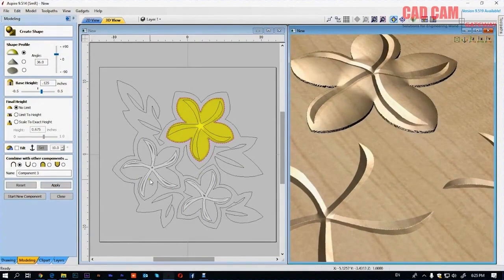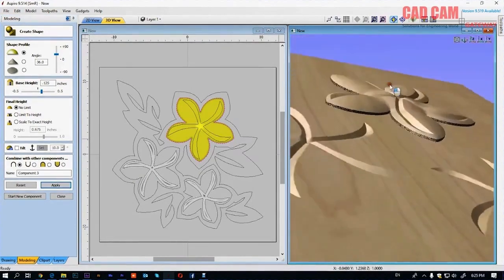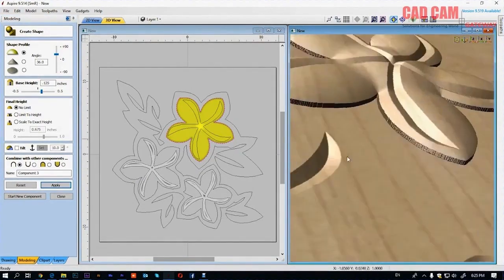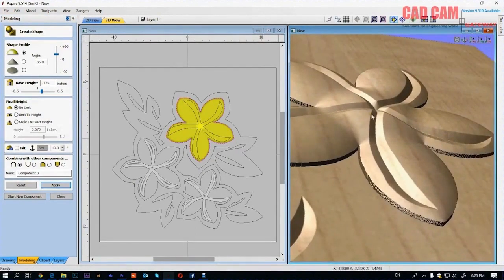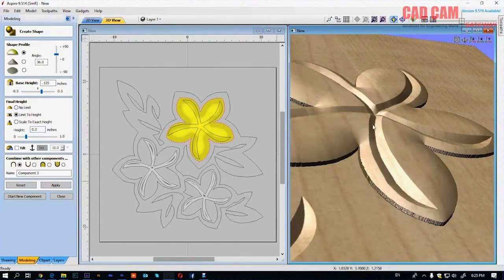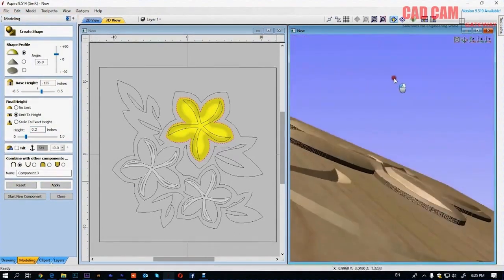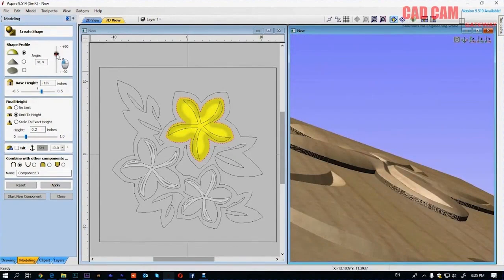As soon as you increase the angle, notice how it has raised this central area even more than before, because the area here is increasing. The more the area increases, the more it raises it. Now, I'll define its height limit here with 0.2. When I preview it, you can see that it has controlled the part in the middle that was a bit bigger.